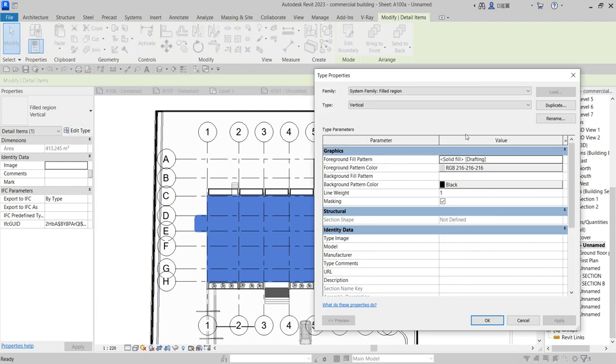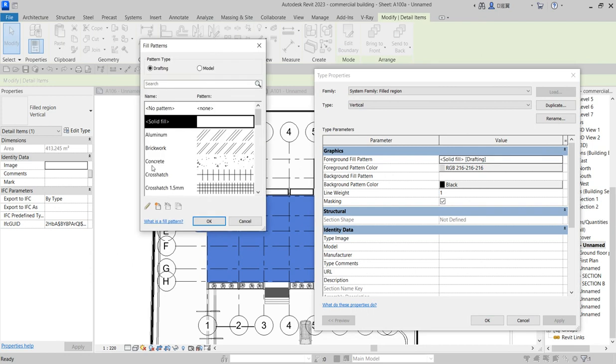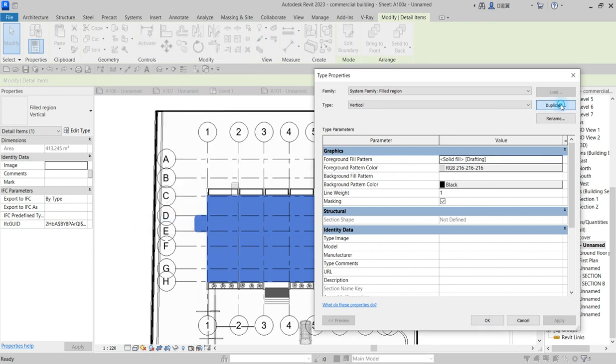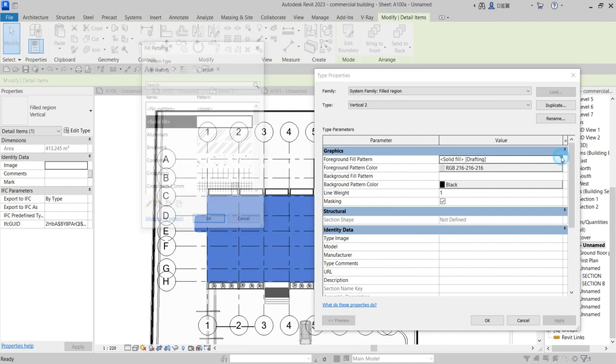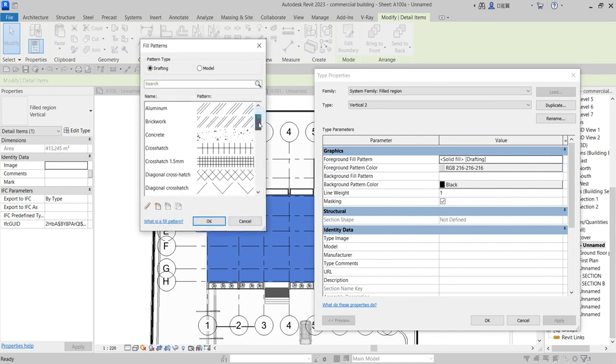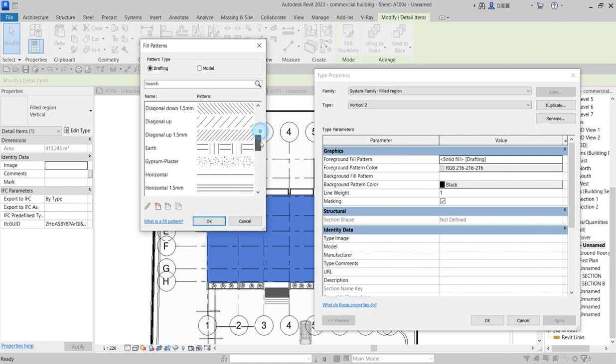So as you have done this one now, click vertical, change the solid pattern to which you want, and change this one for duplicate, so that for the one you have already selected, you don't have any issue against it. So come here and say model in place. If it's a model you want to use, you can just give the fraction since you are only doing it in that particular point. The difference with this one is that when you click on model in place, every area where that model is available, you are going to be seeing them together.